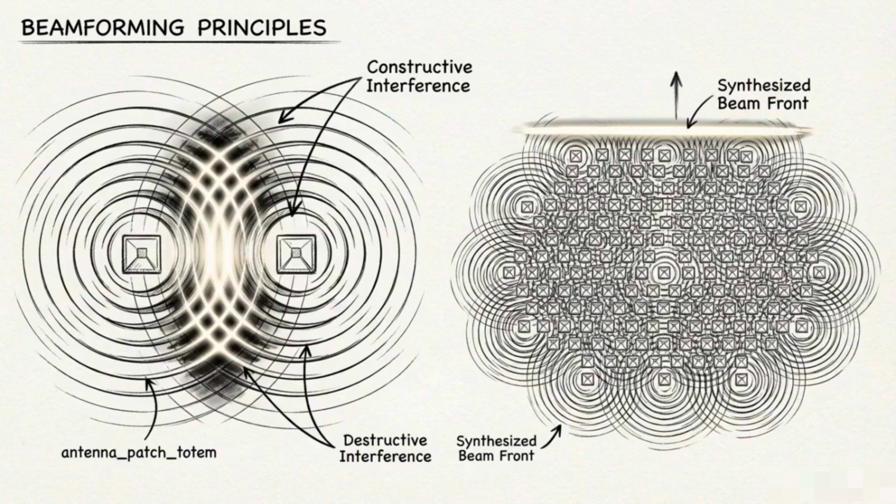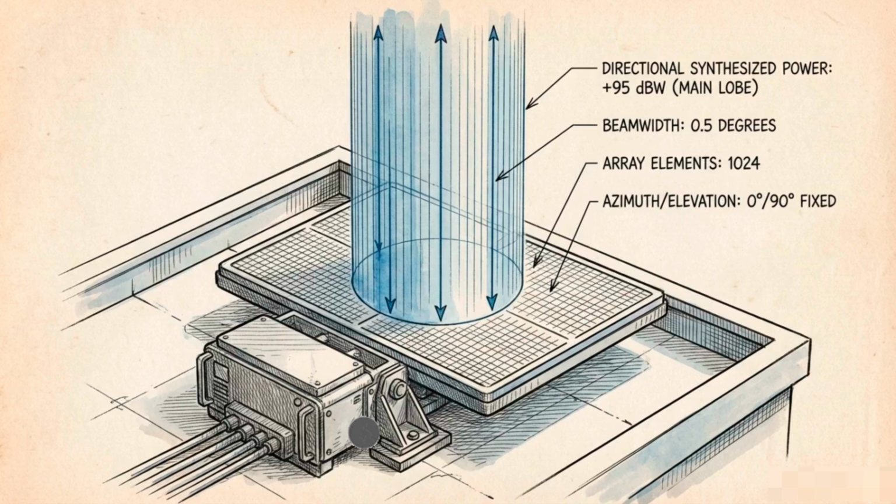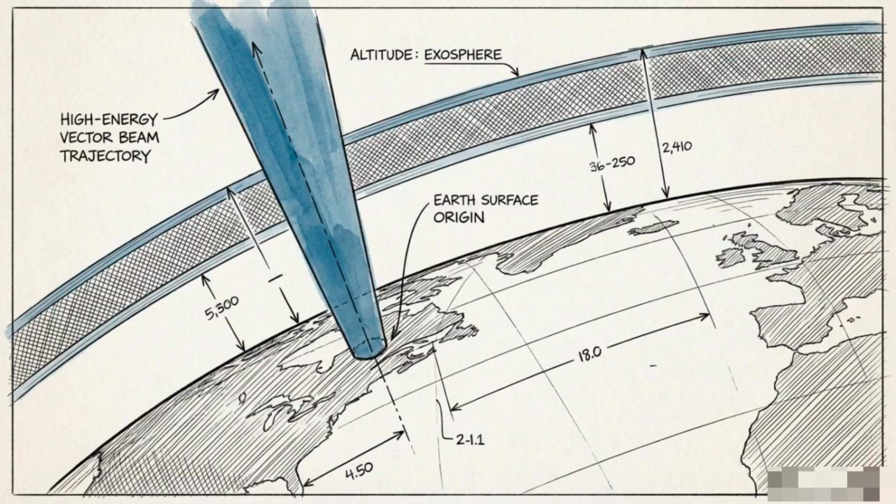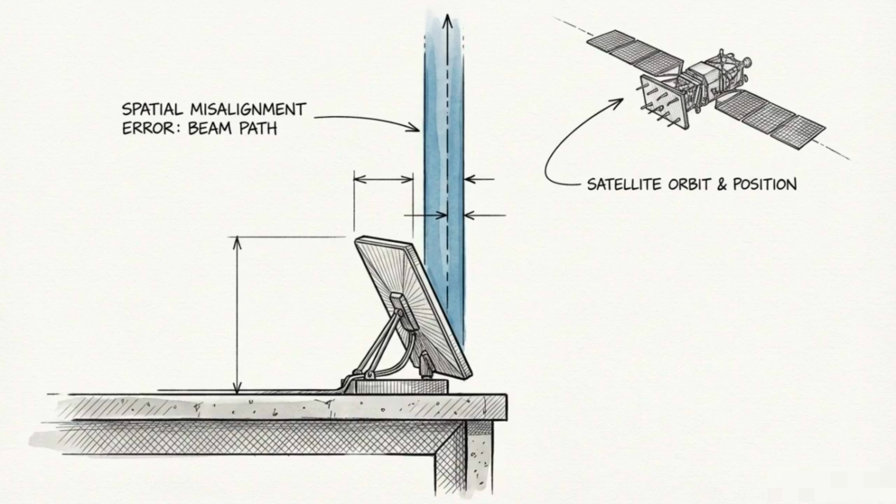When we fire all 1,280 elements simultaneously, the overlapping ripples coalesce into a single tightly focused beamfront. Aligning these 1,280 weak waves mathematically synthesizes a directional main lobe that is roughly 3,500 times more powerful than a single element. The array now produces a beam powerful enough to reach space, but firing all patches at the identical moment shoots that beam straight up, perpendicular to the board.